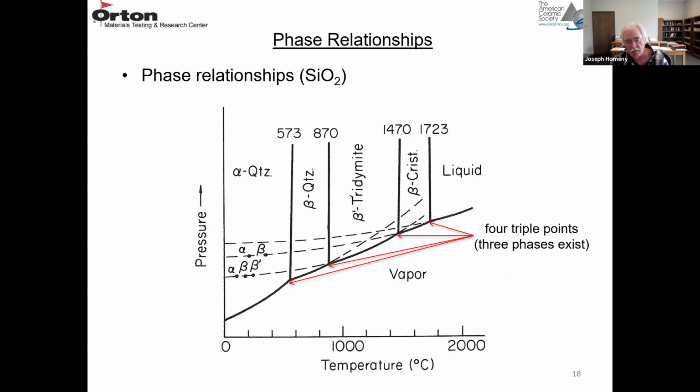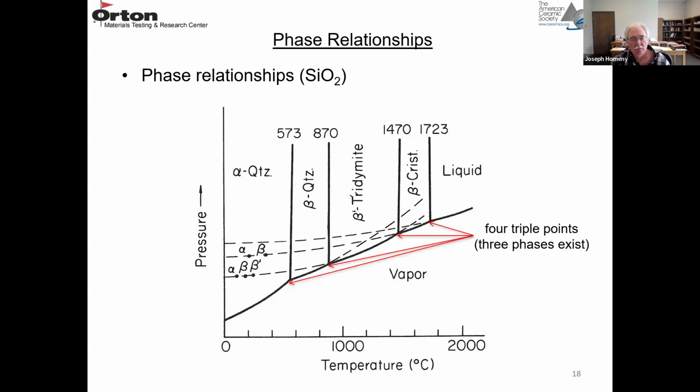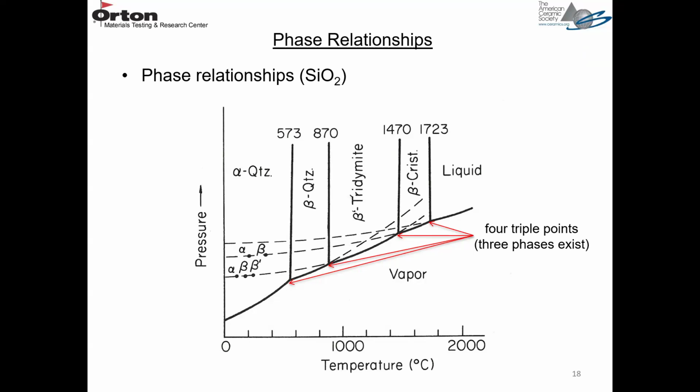So you're right. If you have a silica refractory that has quartz present and you put it in a glass tank roof and you heat it up, it's probably going to disintegrate because of those large volume changes. So you have to get rid of the quartz and prevent those large volume changes. Okay, cool. Thank you.